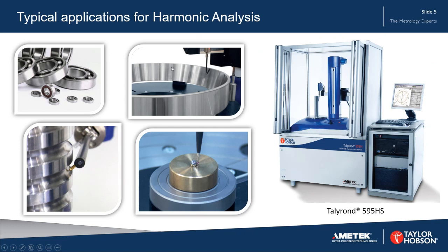Next to it, you can see a large bearing, and beneath it here, you can see a ball screw where we're measuring the spiral harmonics. And here we can see a vacuum chuck holding a miniature bearing. And on the right, a typical instrument with active anti-vibration, a very high precision spindle, able to measure all of these parts.